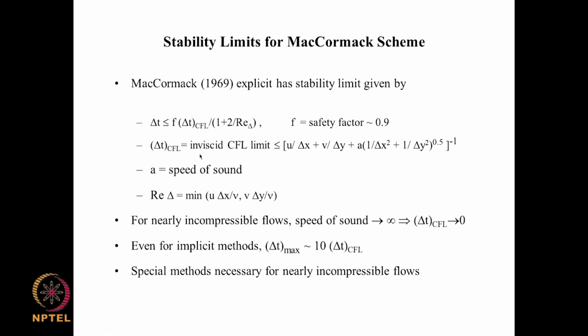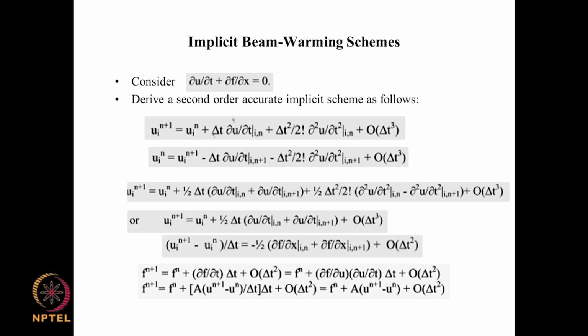And when we look at eliminating this delta t limit, we would like to go from explicit to implicit, and so we are going to look, as an extra example, at a different method, implicit Beam-Warming schemes. It is not a single method, there are variants here, and it is an implicit method. So, one could expect to have no stability condition, but in the actual case we have coupled equations, and when we say coupled equations, we are saying that when we are solving for u, we need to know v, and we are making some estimate of v. It is not the exact estimate, and if you take too large time steps and in the process v is changing, then you could be wrong in the kind of values that you choose. So, even if you have an implicit scheme, you may need to restrict the time step to some values. But an implicit scheme will be better than an explicit scheme in terms of stability limit.